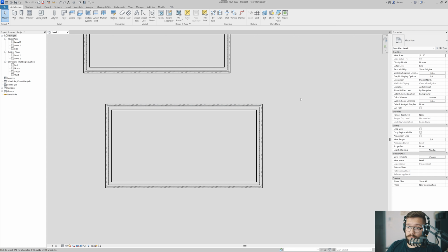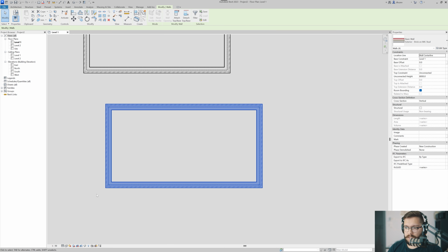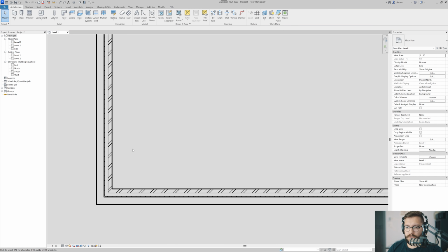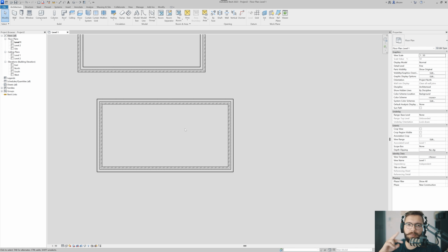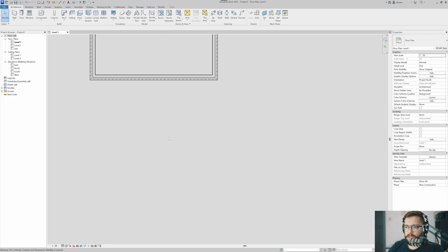A great way to do this very, very quickly is to select one or all of the walls that you want and hit spacebar. This is almost another truism in Revit, that anytime you want to flip something, and this is almost every time, so not all the time, you hit space and it would reverse it. Sometimes it would flip it actually in 4 different directions, depending on how this particular element is created. For walls, it just flips it in and out. That's all you need to know. Okay, so WA,